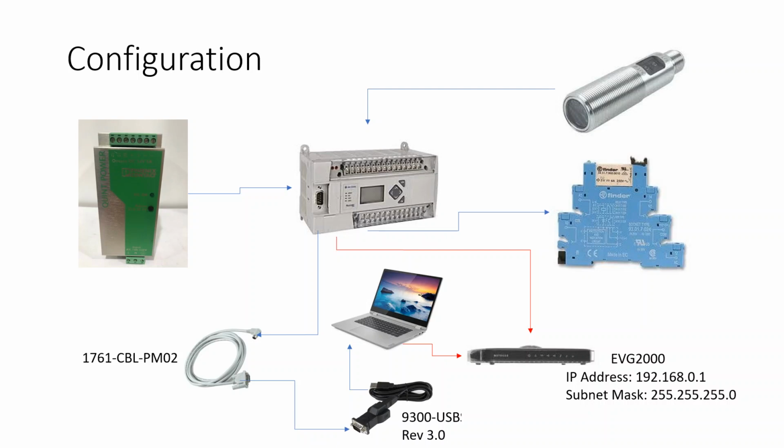Okay, so the most important thing, the biggest benefit of the Ethernet connection to the PLC is when you go outside. Normally, I bring my small $30 router. It's really small and powered by USB, and I connect my Wi-Fi router to the original router inside the control cabinet. Then I can bring my laptop without any cable to any place that has a problem, get closer to that point, and monitor it. I can change the PLC program if I do fault finding. It's way easier, way handier. So normally I do it like that.